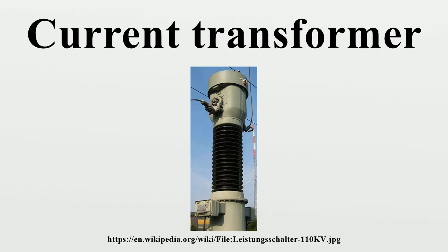Accuracy. The accuracy of a CT is affected by a number of factors including burden class, saturation class, rating factor, load, external electromagnetic fields, temperature, physical configuration, the selected tap for multi-ratio CTs, phase change, capacitive coupling between primary and secondary, resistance of primary and secondary, core magnetizing current.